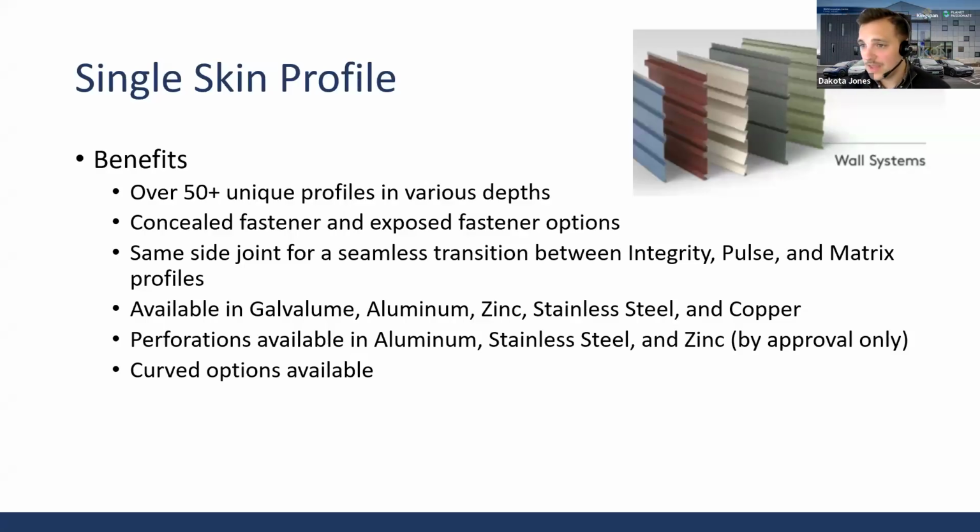The other fun thing we can do. Single skin profile, the last flavor of metal we'll talk about getting on a building, right? Corrugated looks. This is coming back in a big way as people are adopting more of an industrial look in some architectural endeavors, as well as this does a really good job of being practical. Mostly because it doesn't oil can as much either, because it's a rigid material, because it's bent. You can imagine if you fold up a piece of paper, you can't bend it as well as just a flat piece of paper, which ripples quite a bit. You can perforate this stuff, do really high, cool design stuff with it, do all kinds of CNC things. I mean, you look it up and there's all kinds of examples of all the cool things you can do with the various profiles you can use with single skin.